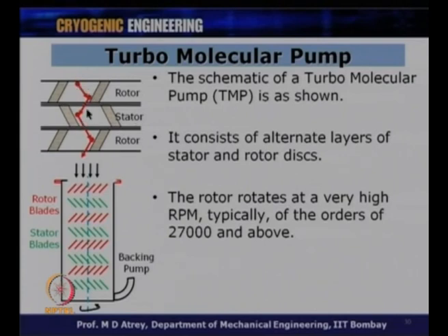To this mass we give a momentum by giving a velocity, and therefore the velocity has to be as high as possible. So the speeds at which the turbomolecular pump works are going to be as high as is possible from a design point of view. Higher the speeds, higher the momentum. Higher the gas molecular size or mass, higher is the momentum.